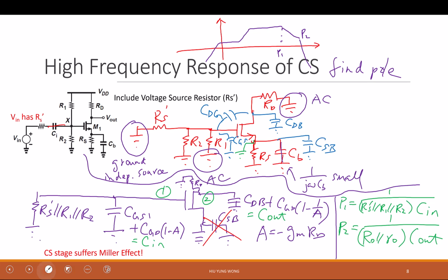And this is the midband region. This is where you want to use. So you design an audio amplifier, maybe this is 10 hertz, this is 20 or 30 kilohertz. And I don't care what is outside, because my voice does not contain this spectrum outside, right?